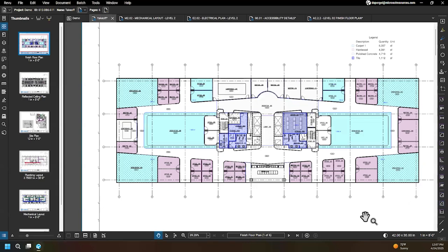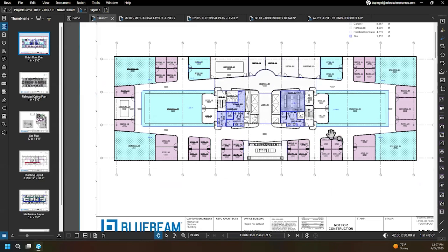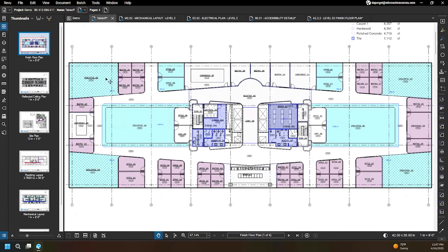All right. So here we have, like I said, first we're going to show you the completed document with a number of takeoffs and measurements already on it. You can see here I have this document open already. It's called Takeoff for what should be obvious reasons. This is the finished floor plan drawing, so you can see that I have a number of different area markups here. Area markups are one of the kinds of measurements that you can create using Bluebeam.